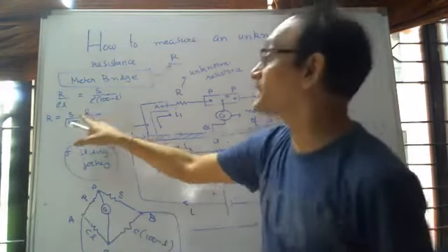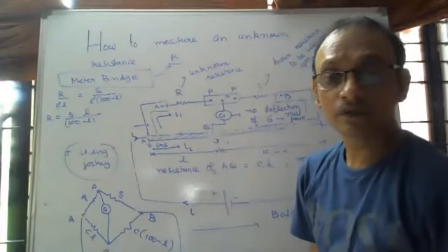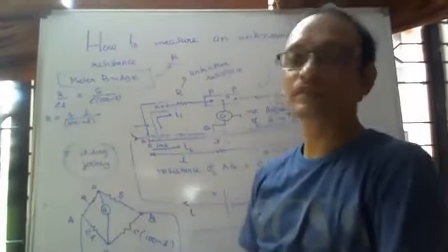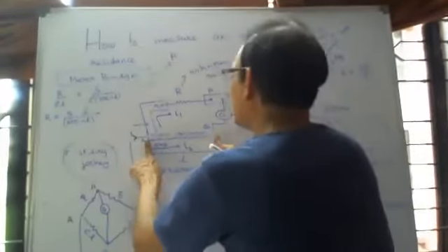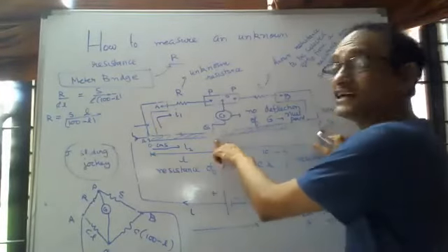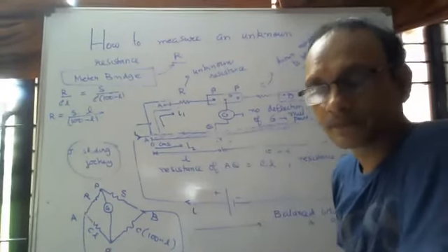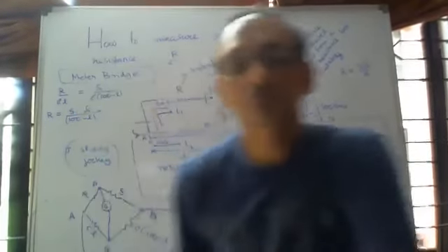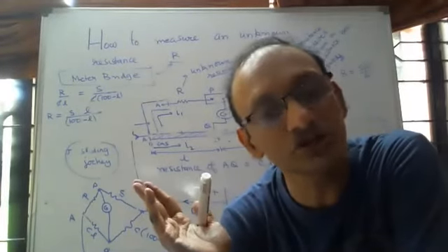That will be S, पता है, length इसके एक्सपेरिमेंट से L निकाल लिया है. We'll compute the unknown resistance from this formula. Unknown resistance would be known resistance S into this length L divided by this length 100 minus L. मतलब if this is 40 centimeters, this will be 60 centimeters, right? As simple as this.